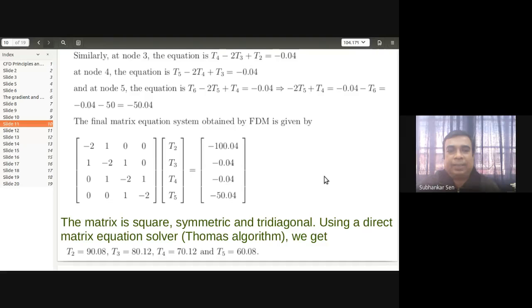So this is an example of a sparse matrix. The beauty of CFD is that it will always generate a sparse matrix. So if you are dealing with a sparse matrix, we should use the iterative methods. In iterative methods, we need not store these zeros. But if you use direct methods, you have to store these zeros. So your computations will be expensive. So it is better not to use a direct method.